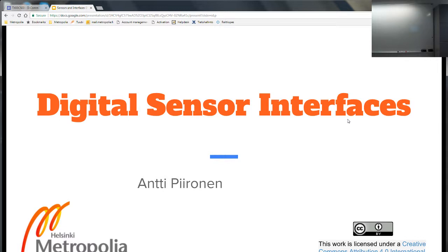Yes. Okay. So OneWire, simple to connect, a little bit heavy on the protocol side, although there is plenty of sample code to do it, and in PSOC there is a module to do it with all the APIs. Then the I2C, a robust bus for, say, slower data transfer needs. Then the SPI when the speed really matters. The SPI is a little bit heavy.